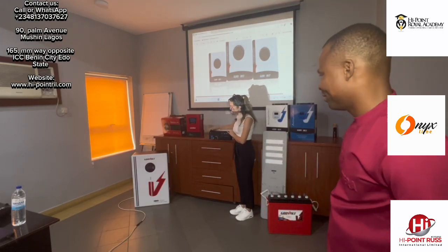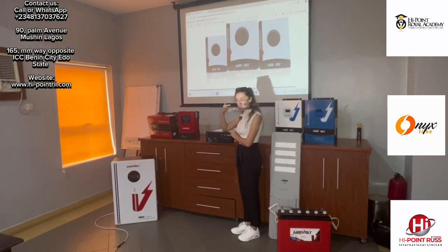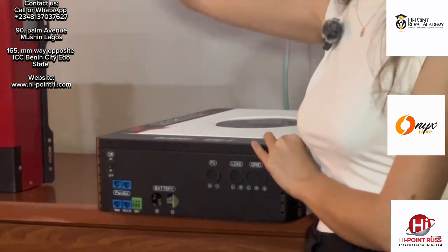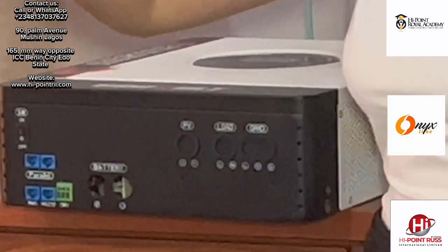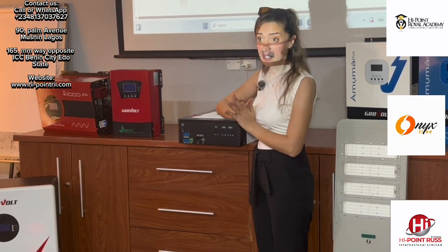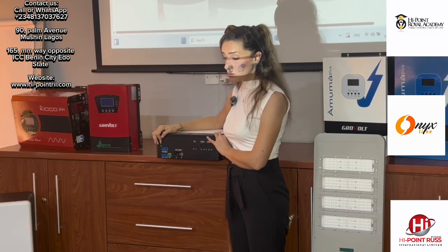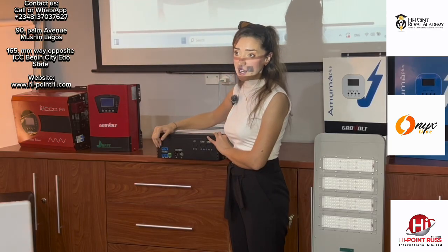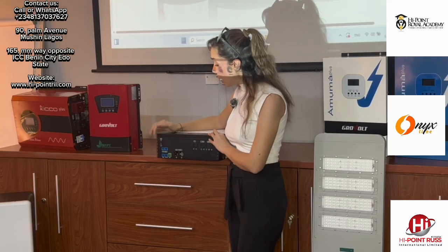Let's see here. The inverter is on and off. But also, I want to mention this now to remember it when we ask. The function in AMOMA and RICO, if you turn off the inverter, has bypass mode. You know what bypass means. Engineer Russell explained about that. But this inverter, if I turn it off, no output. No bypass mode in this inverter. If you turn off the inverter, the output is 0. No output at all. Okay.